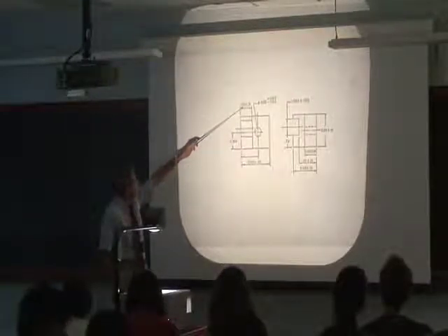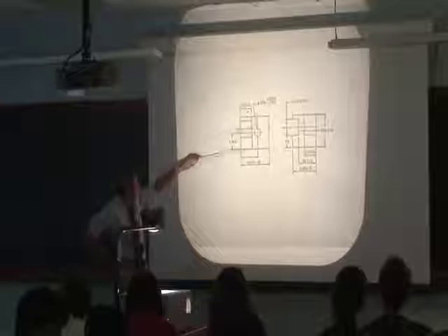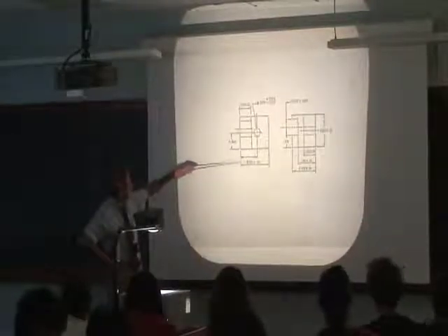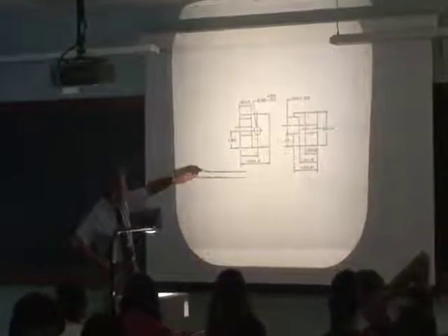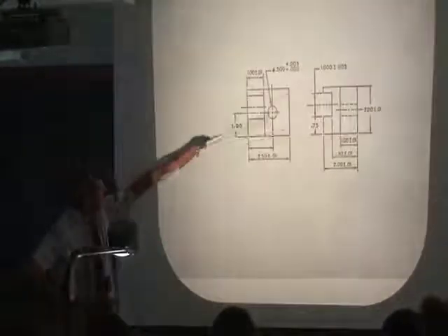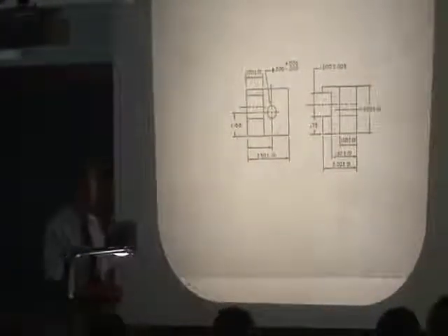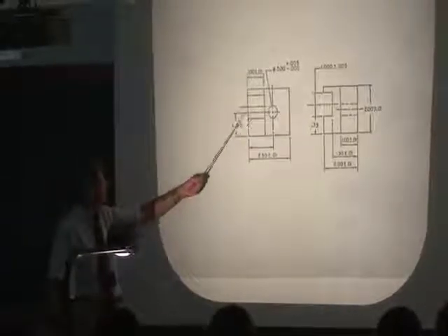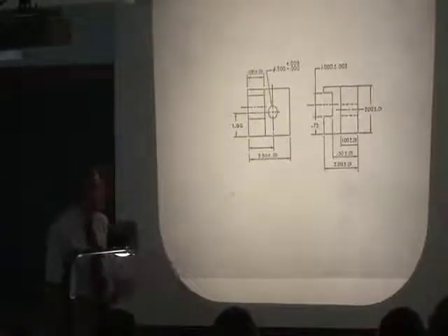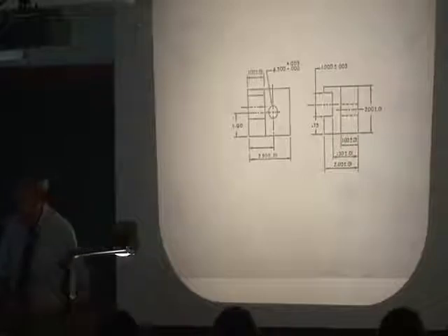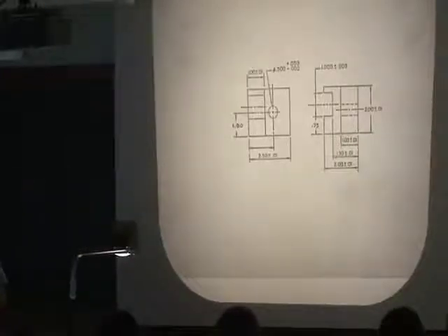You see things like 1 plus and minus 0.01, 2.5 plus and minus 0.01, etc. Here's 1 plus and minus 0.005. And these gave you ranges of allowable variations of the dimensions. And this is what industry ran on from the late 1800s up through the Second World War.